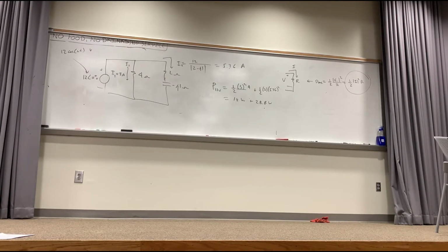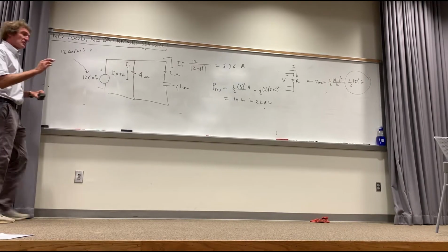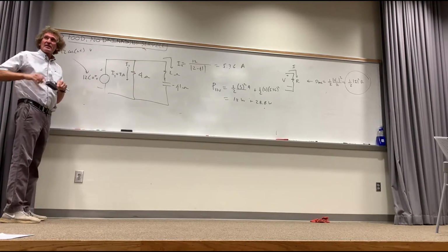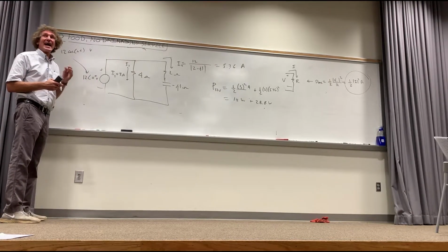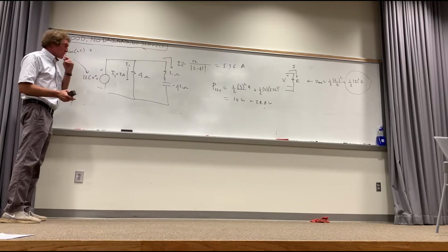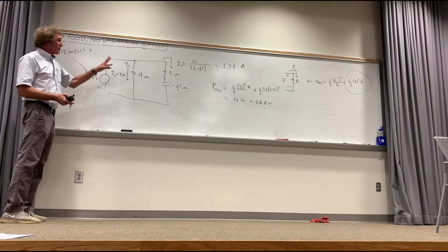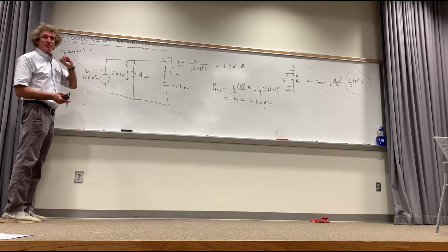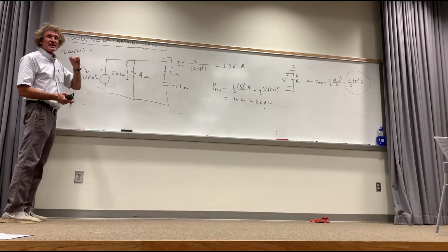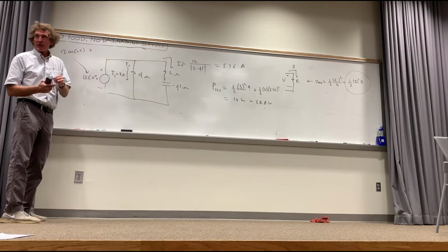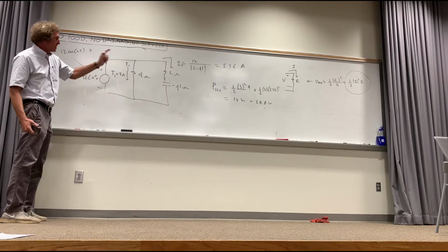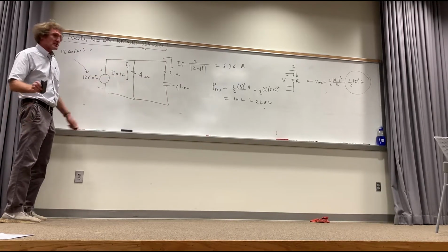Next concept, because there's stuff I'm going to show you, and I'll tell you what's really important. The key to take from this is, when you want average power, which we always want, you want to find the current, and once you've got the current, you just take that current, square its magnitude, and multiply by the resistance, divided by 2. That's the power in each ohm, got it? But you have to get the current. That was the bottom line of this. And the average power dissipated by capacitors and inductors is 0.